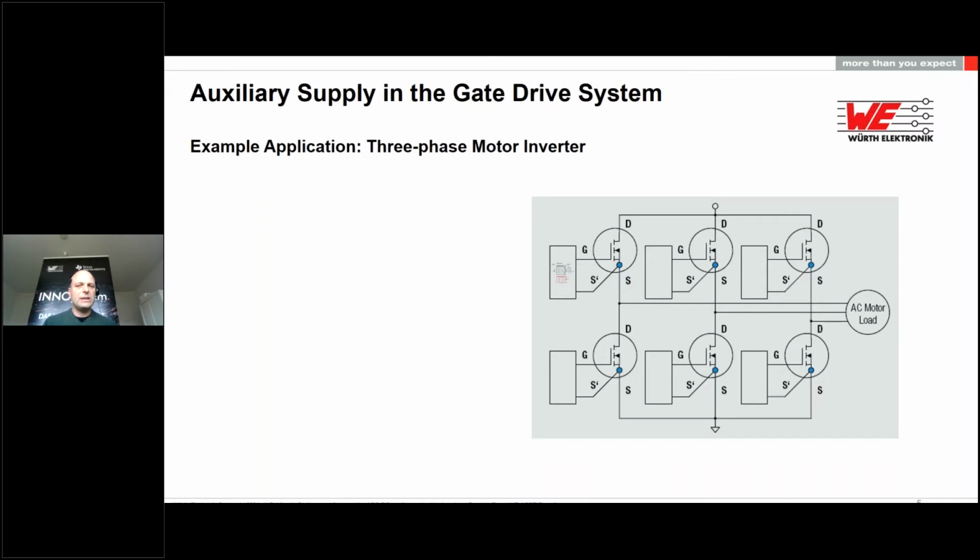For a better understanding, here is an application example for powering an AC motor load. The high power brushless electric motor needs a minimum 3-phase alternating current power source, but the available power might come from a DC bus, direct current form, like after a PFC stage, or from a battery.